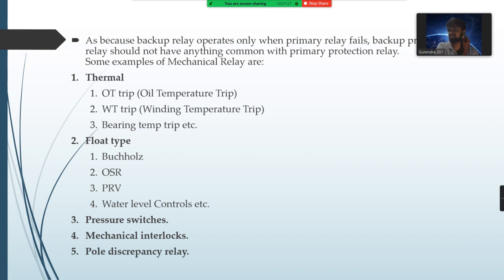Because the backup relay operates only when the primary relay fails, the backup relay should not have anything common with the primary relay.